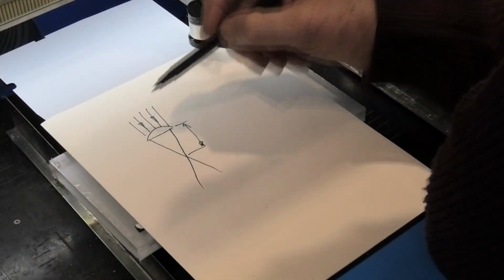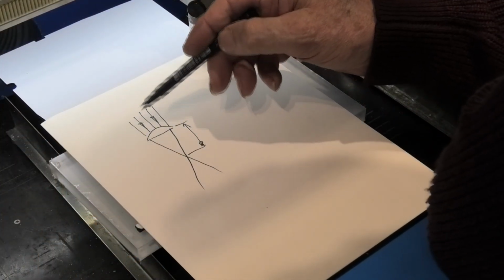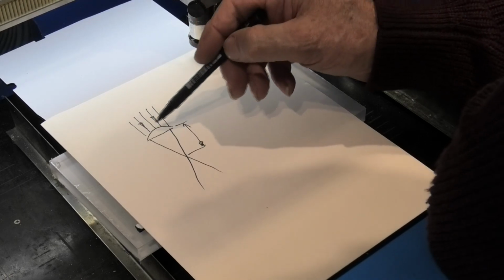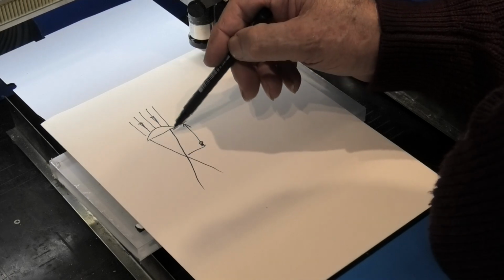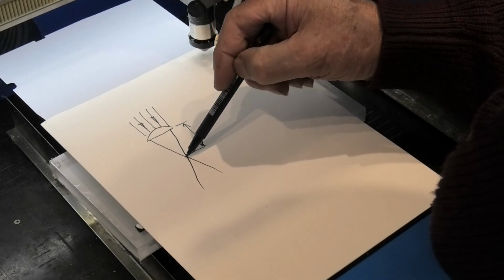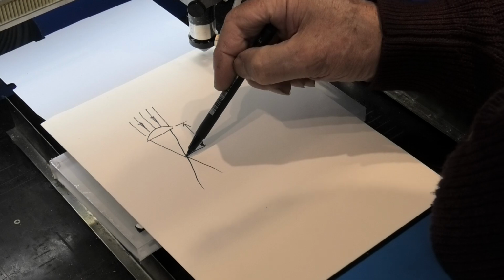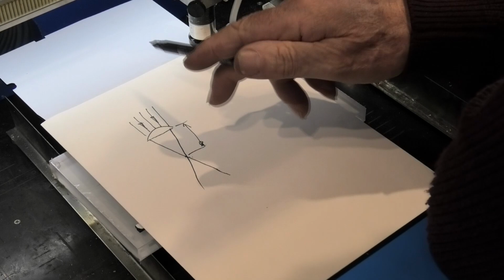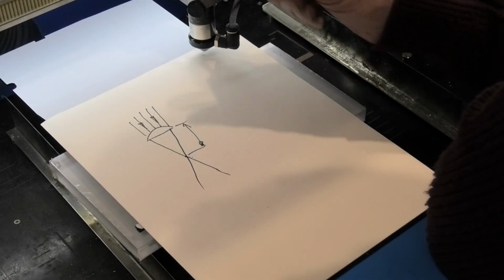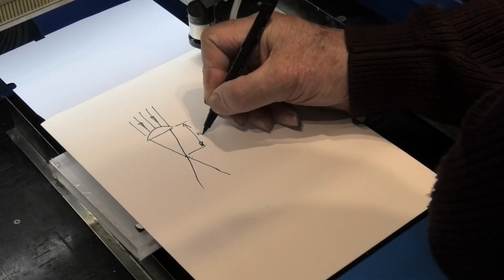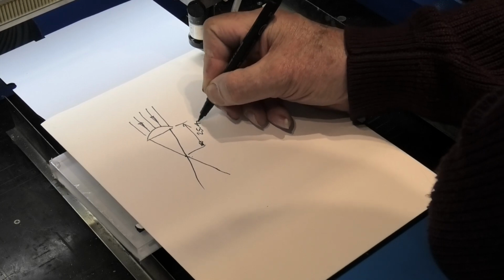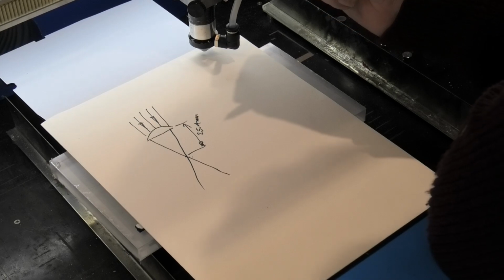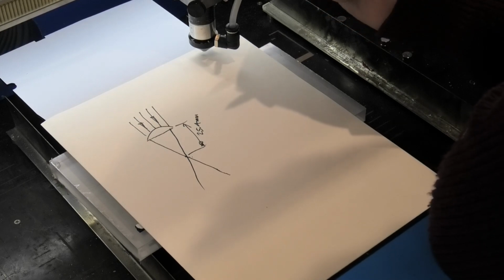Everybody knows that a lens looks like this. Parallel rays of light come into the lens from the laser source and then focus down to a focal point. And then after the focal point, they expand again, like that. In this particular machine, I've got a lens which is only 25.4 millimeters focal distance. That's very, very short. That's one of the shortest lenses that you can buy.